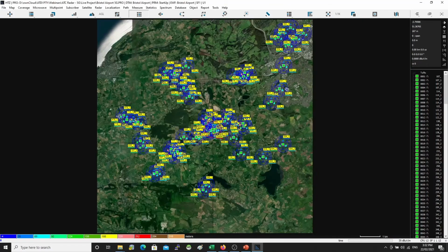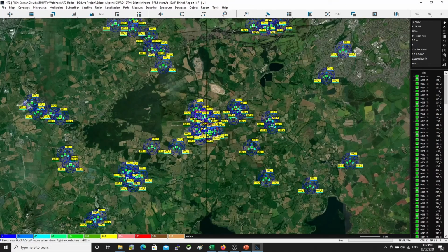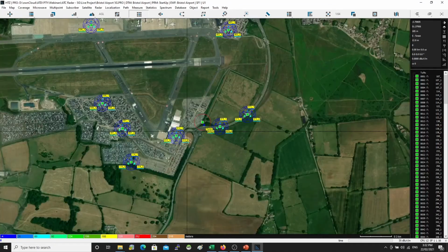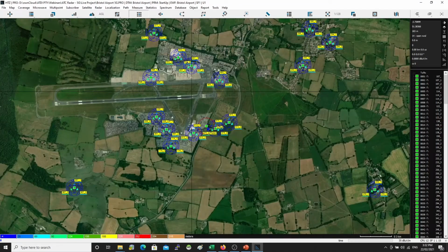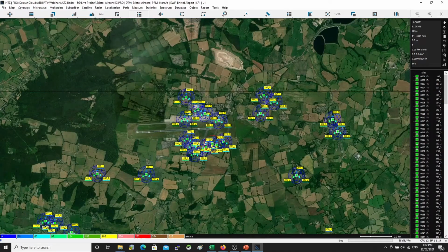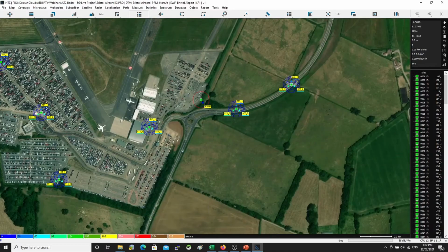Now, the sites are there, the radar is there, and that vector. So you said we're going to do the vector. I will show you what the idea is here. I want to create circles at 1.5 kilometers and at 7 kilometers. Now 7 kilometers is the range where you need to coordinate with the radar if a 5G site is being deployed within 7 kilometers of the airport. 1.5 kilometers is a sensitive area where we treat propagation as line of sight only, and we look at the reflections as well.